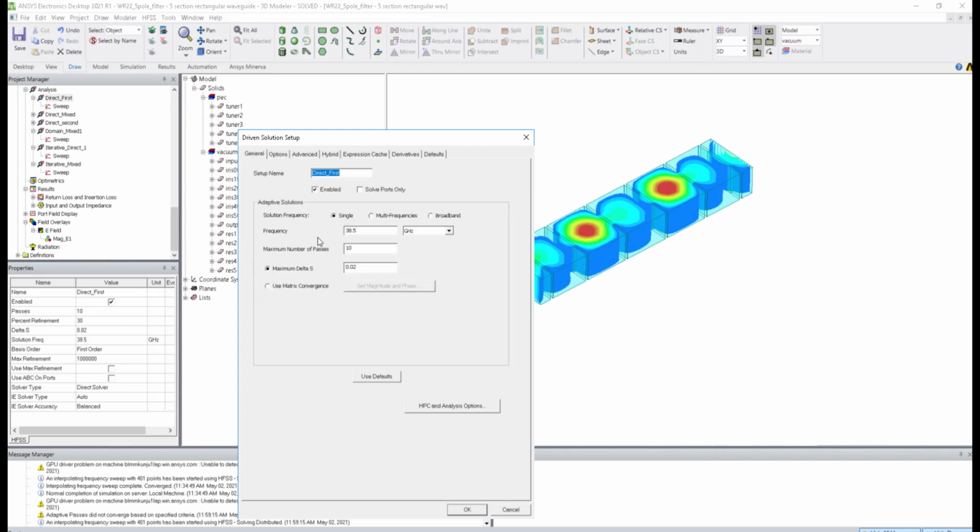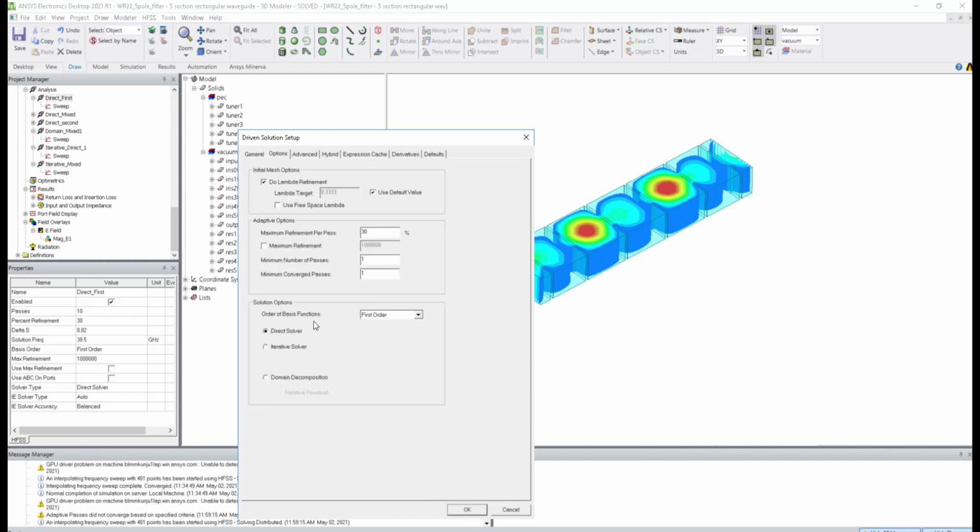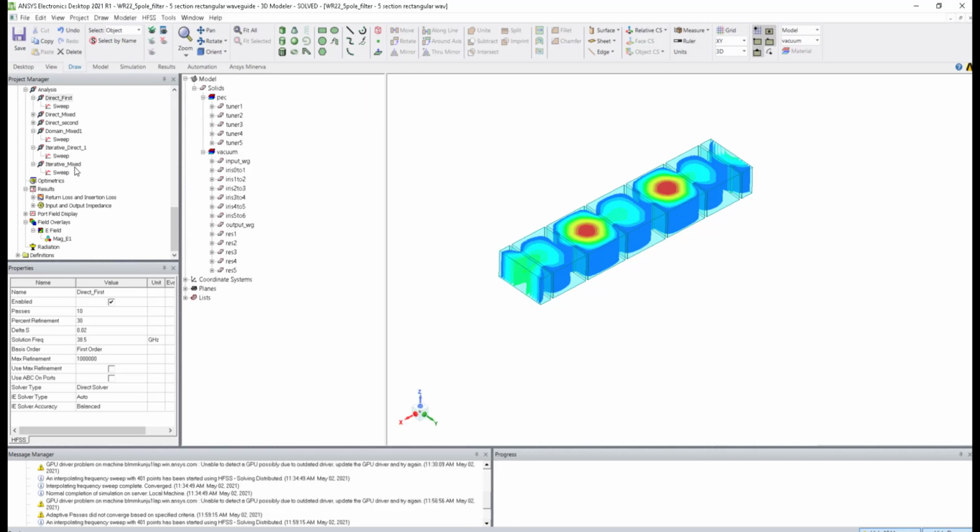These are all the simulations which I tried to summarize in that PPT. So play with this area, and it depends. It's sometimes very difficult to say which solver will be good, but take one model and see which solver performs with lesser memory and lesser time, and choose according to that.